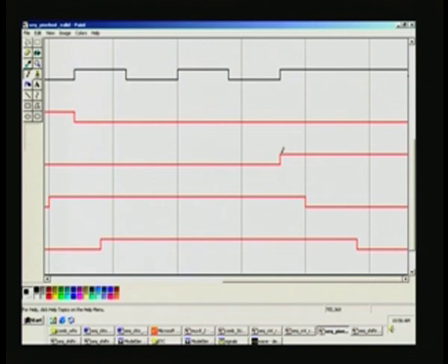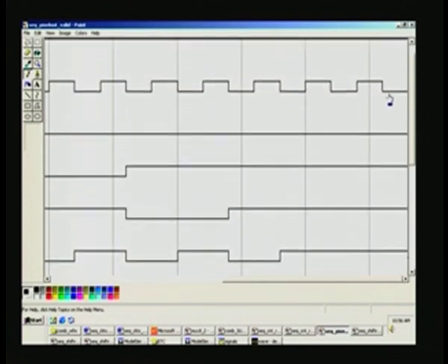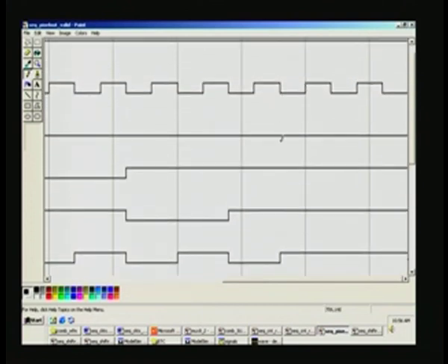So, this is the reset pixel out. Because it has gone high, it is going low, but it has to be synchronous with the positive edge of the clock, right. This has happened right here, but it will not take action here, only at the positive edge of the clock can I take it. On the other hand, had you decided on a negative edge transition, you could have written a negative edge instead of positive edge in that always block, right. But for the same signal you should not put positive edge clock and negative edge clock, it is a violation, right. Tool will reject that.